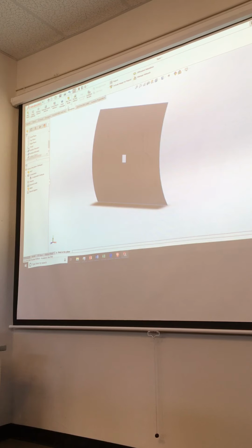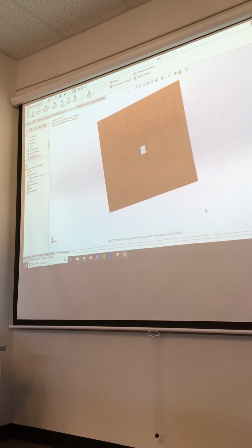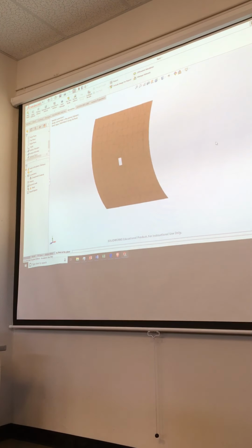Okay, so if we mesh this, actually didn't do bad there. It didn't do the other part, so sometimes it will, depending on how it feels about it. If you want to, there's an exclude from the analysis flag, right? That you can go, don't mess with this surface, right? Okay, and it won't mess with it. That's an interesting part there.